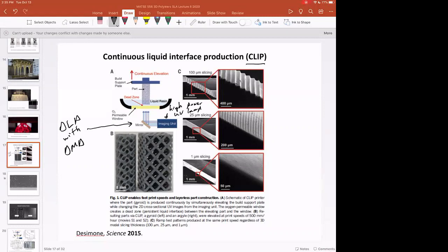And it uses the exact same DMD. The innovation that has occurred recently in some of these high-speed printers is the DMDs are UV hardened. And with a high intensity power UV lamp with an even illumination field, basically all you're doing is projecting an image in UV. And the image is ones and zeros, or it's black and white. And that's what does the photopolymerization patterning in this process.